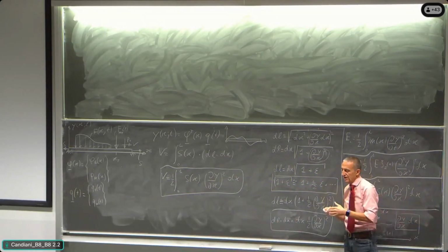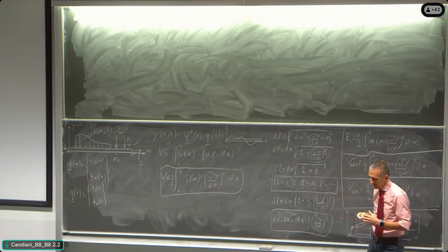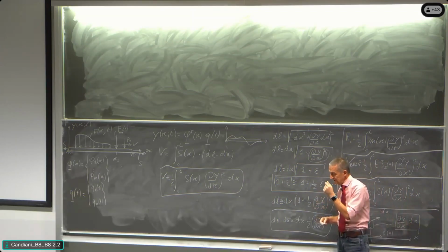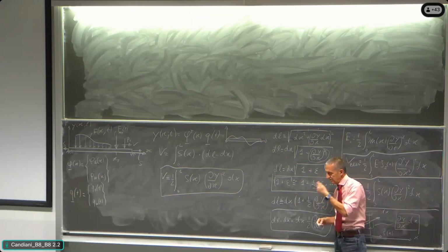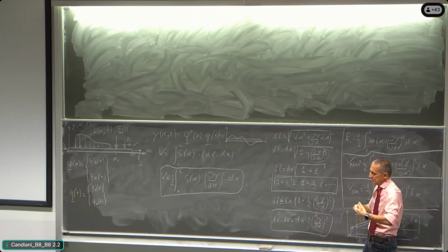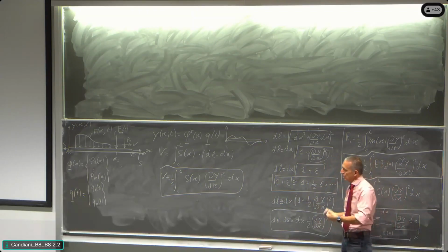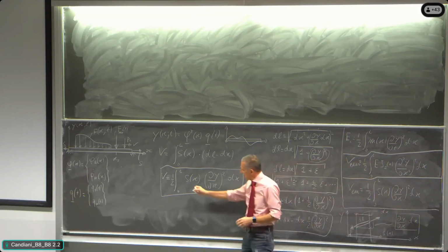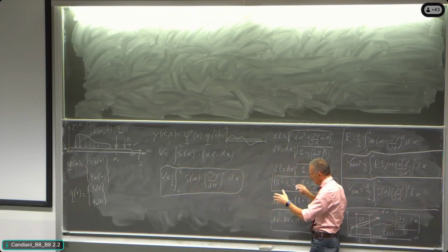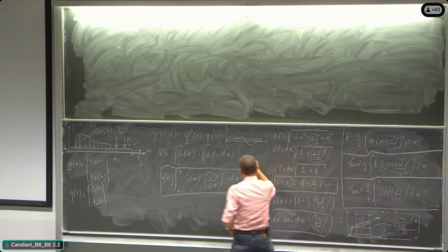So we are considering that the axial internal action is not changing because of the movement, it is constant. Instead, it is changing a little bit, but it is an infinitesimal of superior order. And so we are considering that the first order quantity is the work done by the axial action that is undergoing an elongation of the element.